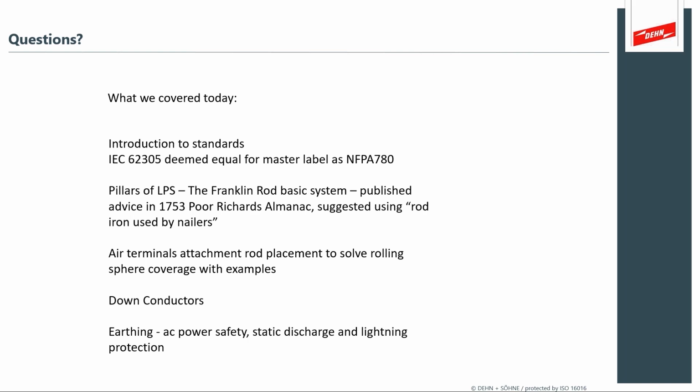And a really nice question that we have here is, can the HVAC ducting be used as down conductors if the sheets mentioned comply to the IEC standard thickness? HVAC is notorious for very poor interconnected bonding. Even if the material is thick and robust and meets the standard minimum thickness, what you see in HVAC is folded and crimped joints that aren't actually very well electrically bonded together.